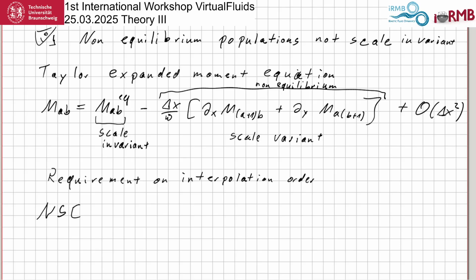We just look at the Navier-Stokes equation because this is what we want to solve. I'll simplify the Navier-Stokes equation now into a material derivative. I just write a material derivative here on the left-hand side. And here we have c_s squared times the gradient of rho, which is the pressure, and I multiply by rho 0 on the other side.